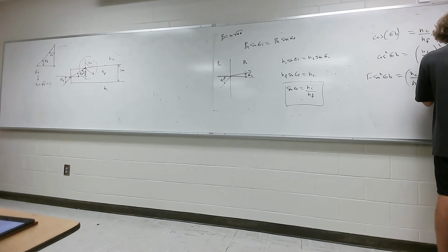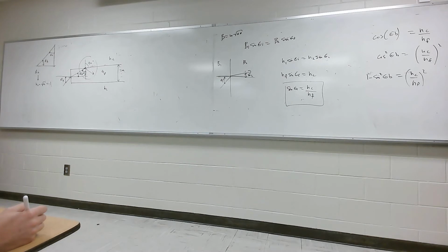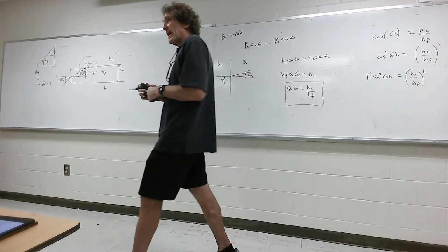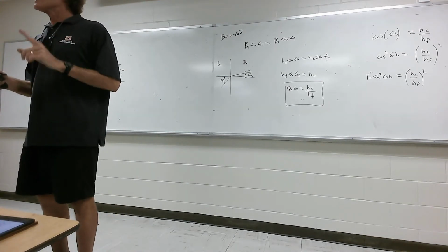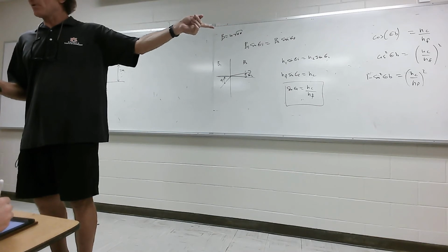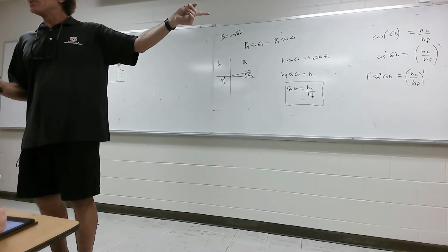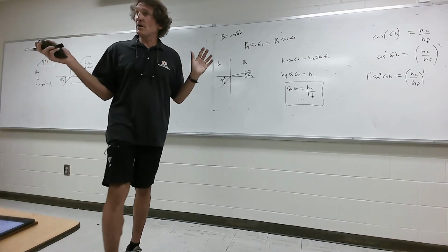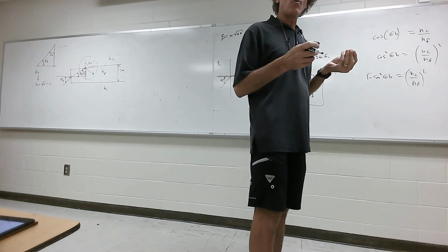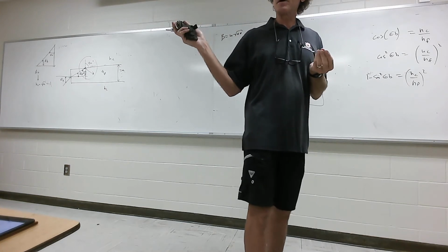The sine of theta b is equal to the square root of 1 minus nc over nf squared. Just for a second, I'm going to make mention of something. You see how you have nc over nf? If that isn't less than 1, that's going to be a square root of a negative term. Y'all follow me? Square root of a negative term is j. It makes no sense. You can't have it. The only way you're going to get propagation is if nc is less than nf. The fiber core has the higher dielectric. Everybody with me on this class?